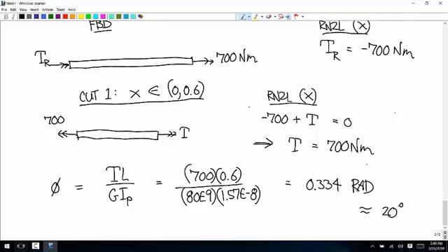And so even though you have a big macroscopic deformation, you have really small strains. That means you have small stresses. And this is still totally in that linear range. We're still not talking about permanent deformations. If you let go of it, it would happily go right back. And you've seen that happen with torsion springs. It's sort of the same idea.